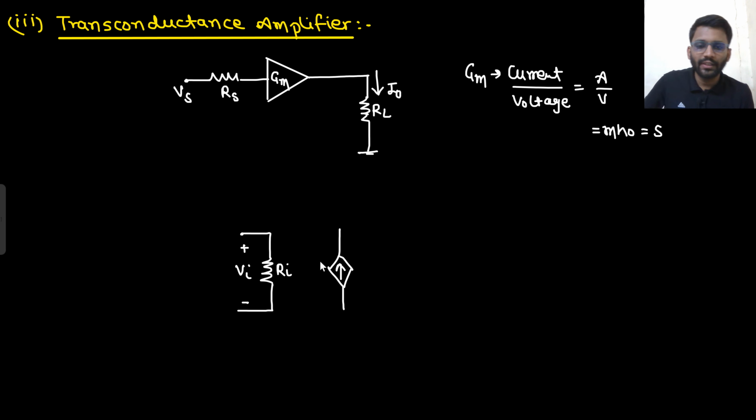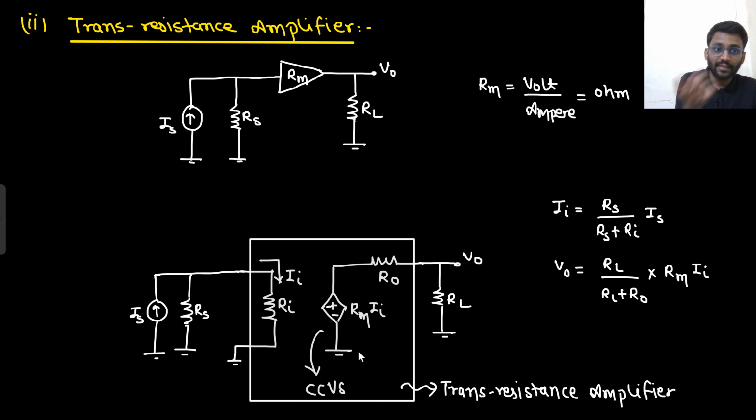So it's just the way of showing it, that your amplifier is working such that it is giving you a voltage from plus to minus. Upper one is plus, lower one is minus. You can make an amplifier that gives you negative gain. What is that amplifier? Do you remember? Common source amplifier gives me negative gain. And now let us assume this can be a common drain amplifier, which will give you a positive gain, or it can be a common gate amplifier as well. That also gives you a positive gain. So the direction doesn't really matter.